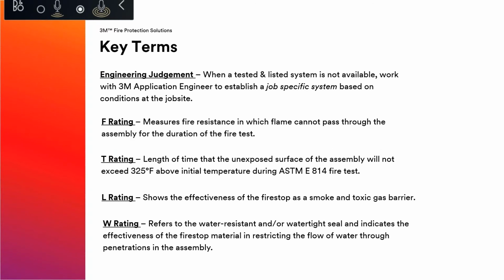Some key terms, we've touched on a few of them, but these are the primary terms when referencing the appropriate system. F rating, that's your hourly rating. The system will identify the F rating capabilities. Typically most construction types are within 1 to 4 hours.